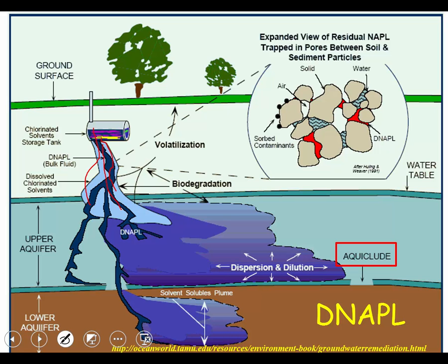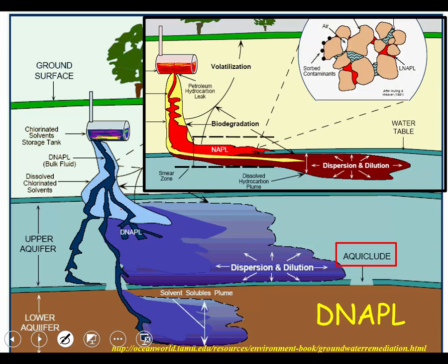Of course, they're dispersing and diffusing, but we also have a problem in that these aquicludes sometimes have holes. And so these aquicludes, which are better said aquitards, can also be breached, and when they breach, then we get these dense NAPLs, not only polluting a large area of the unconfined aquifer, but the confined aquifer as well. And this is kind of a worst case scenario. Okay. And of course, it's a very different type of pollution than we get with the light source.